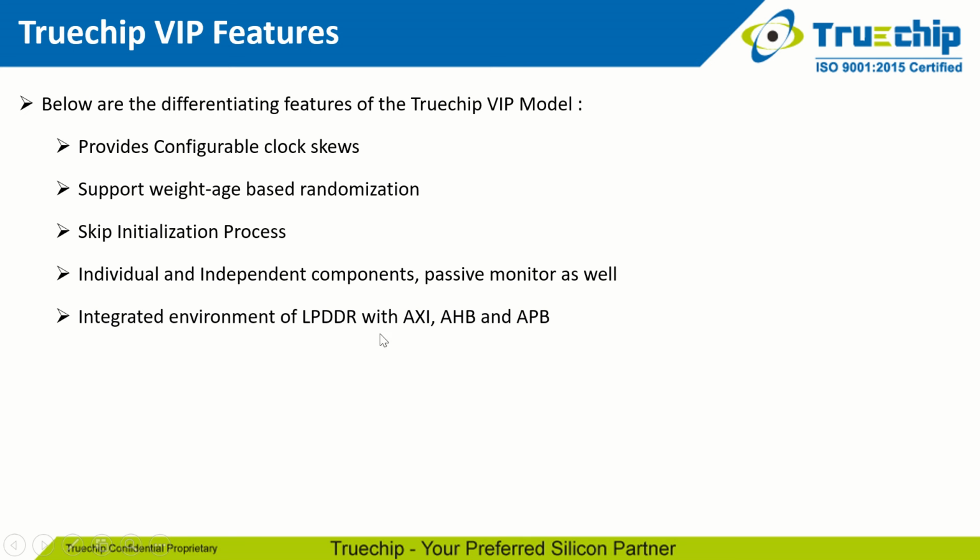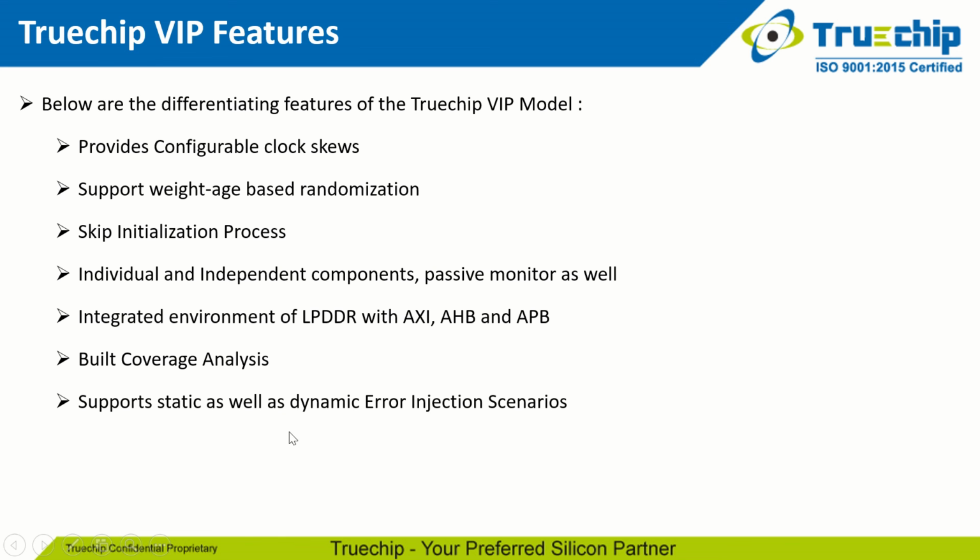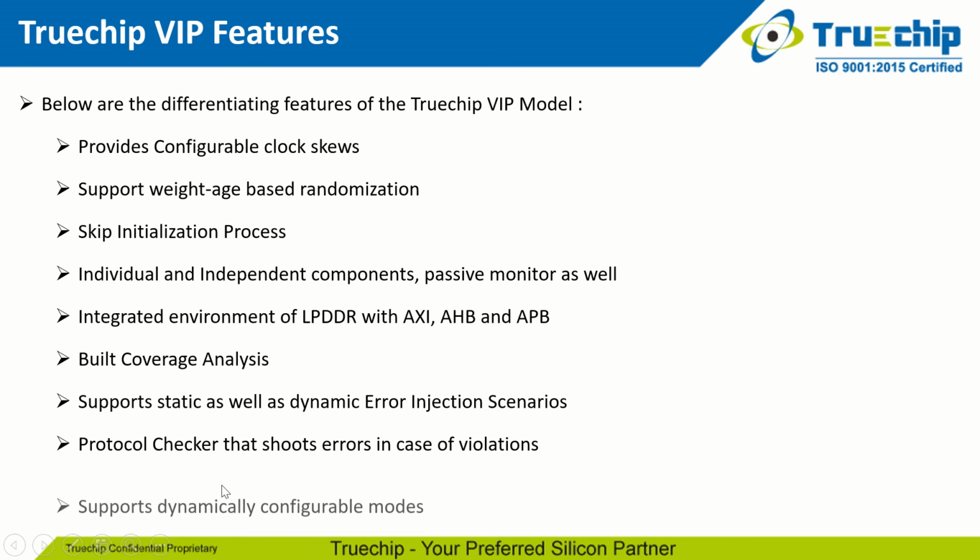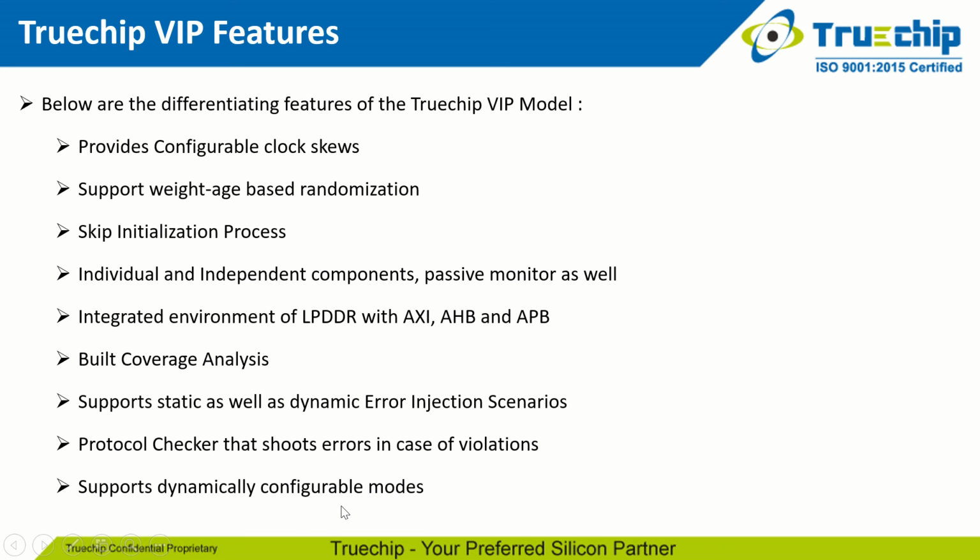Integrated environment of LPDDR with AXI, AHB and APB. Built-in coverage analysis for the whole LPDDR5, which covers all features. Support for static as well as dynamic error injection scenarios. Supports a protocol checker that shoots an error in case of violations. Supports dynamically configurable modes.